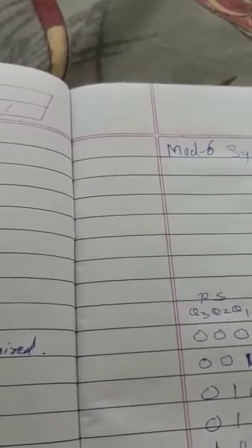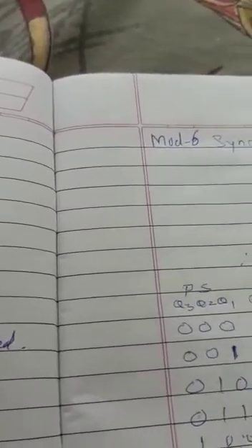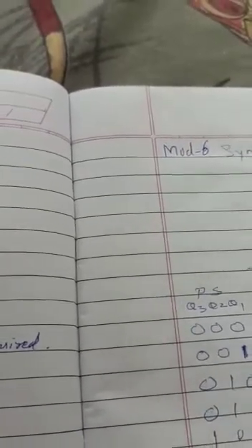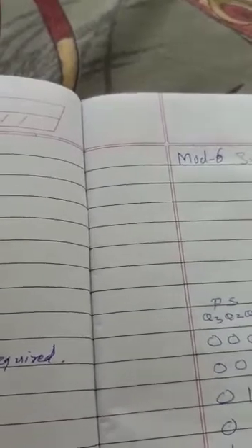It means that clock is given to the first flip-flop, and output of the first flip-flop is used as a clock input to the next, and output of the next will be used as a clock input to the next, like that. Means we don't clock all the flip-flops simultaneously. Means the clock frequency of the clock input of flip-flops used will be different in case of an asynchronous counter.